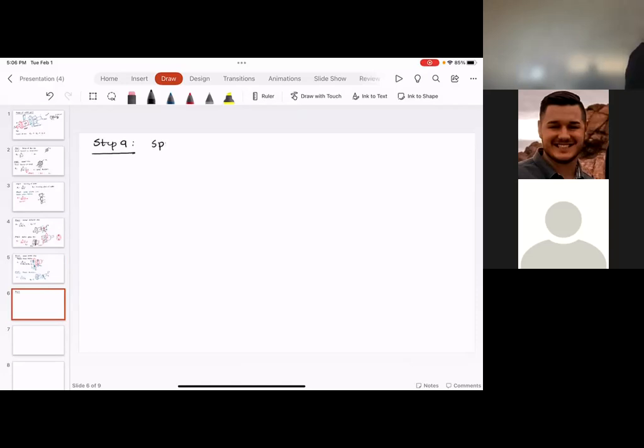Spigot collar dia. Please understand, Spigot collar dia would be determined because of the crushing. So crushing failure, and that is sigma c